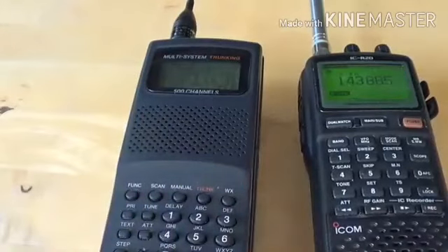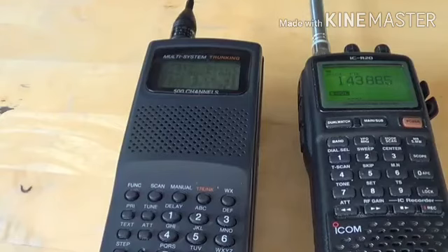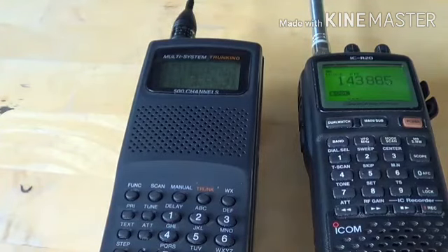And of course, on some scanners, sometimes with signals that are very strong, you might want to set the squelch a little higher to prevent, for example, some interference. Maybe you have a local noise and your noise level is a little higher. Then by putting the squelch a little higher, you will prevent the noise from actually being heard through the radio, and any signal that's higher than the noise floor around you will be heard on the radio. So squelch is very important. In general, you want to set it at the lowest setting possible, not really much more than that.